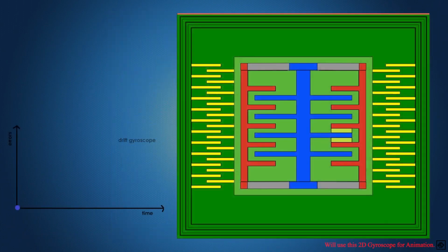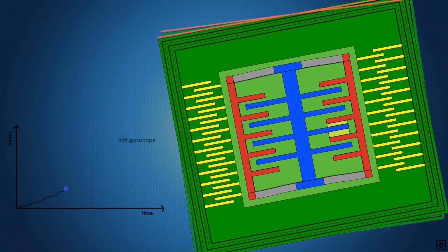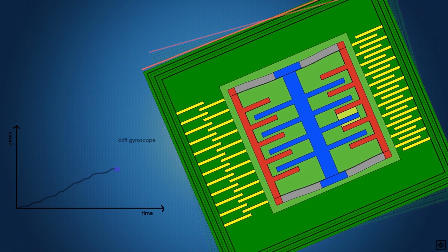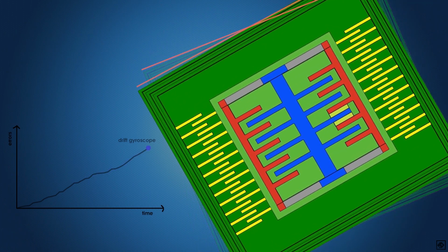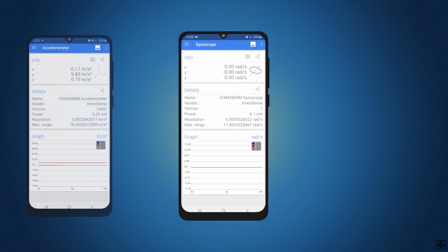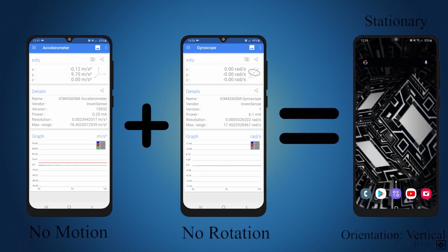But the gyroscope is not affected by gravity, so it has to reference its position on itself. The current rotation is based on the previous rotation added with the detected change in rotation. Over time, errors will add up. Hence, drift will occur. The gyroscope itself is not enough to calculate the true rotation of the phone. Due to these uncertainties of accelerometers and gyroscopes, they apply a principle called sensor fusion, in which they combine data of different sensors to achieve a much more certain outcome.